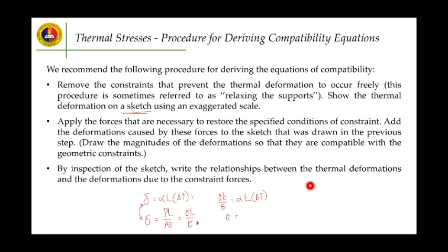So stress is equal to alpha E change in T. So this is now the formula for a typical thermal stress for materials that are free to expand. However, it changes when the material is restricted, and we have examples for that.